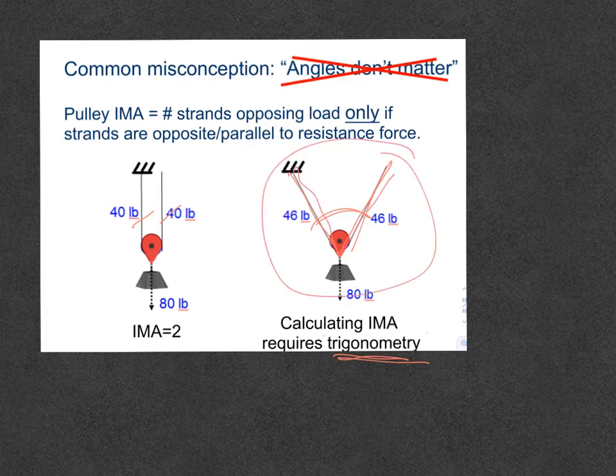See, examples. Now, in the future, you're going to be designing compound machines. So if you are planning to put a pulley into your compound machine, you have to make sure that the strands are parallel, so you can calculate the actual mechanical advantage and the ideal mechanical advantage. Otherwise, you're not going to be able to do that. Or when you do that, applying the formulas that you have learned, you're not going to have a reliable result. Okay?